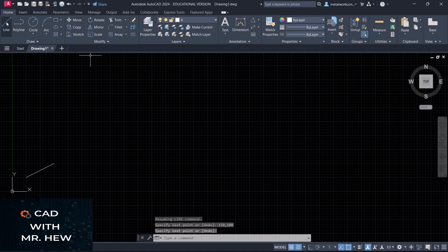All right, let's go again. Line. We're looking at how we draw a line in AutoCAD at an angle to the horizontal or vertical plane, like the graph paper, x-axis and y-axis. So let us choose a point. Choose there. All right. So another thing we can do is go relative to the point. So we can put in the actual coordinates relative to this starting position.